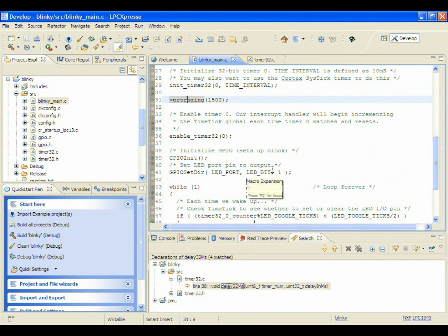I am having second thoughts about all of my edits to the Blinky example. Right about this time, I am wishing I used version control. Actually, I have been using version control. There is a built-in revision control system in LPCXpresso. To use it, go to the Project Explorer, right-click on the file, and choose Compare with Local History.